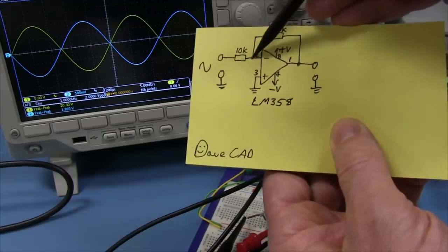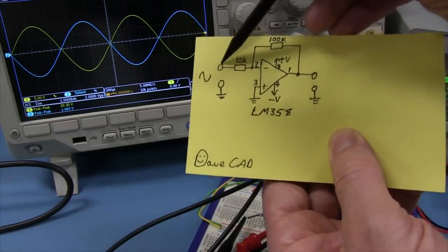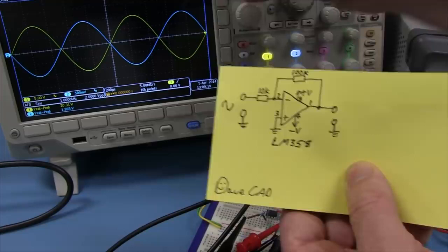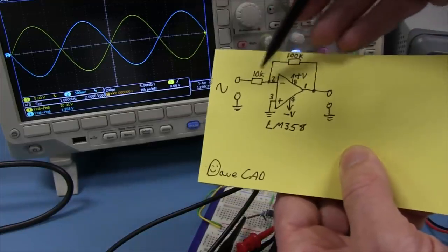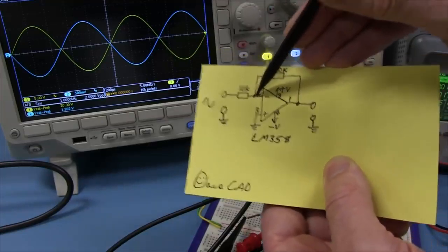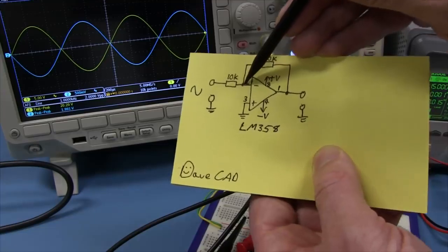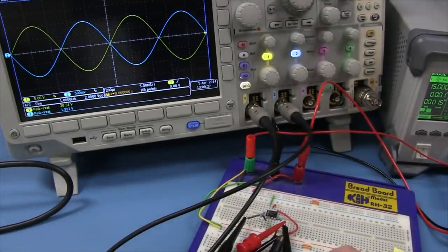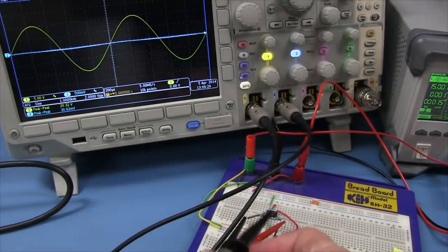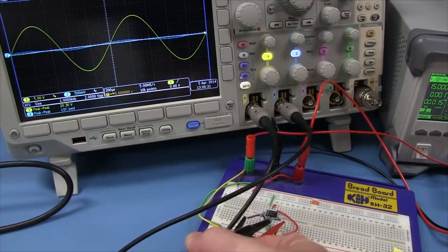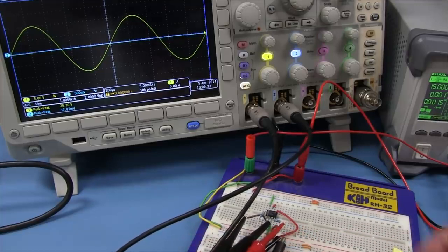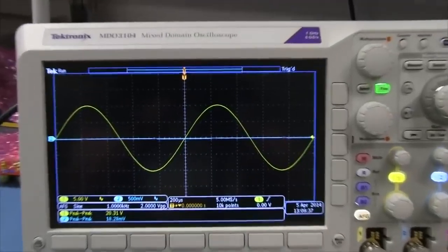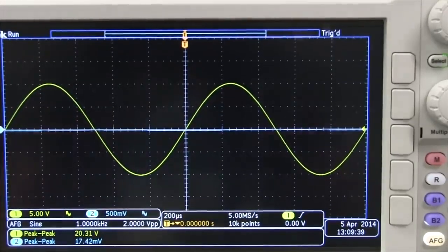Now, you wanted to see the virtual ground, didn't you? What happens if I move my input probe, the blue waveform here, from the input over to this? You'd expect to see the signal. But as I've told you, and as you should trust me, let's move the probe over. That is our virtual ground point. Look, flat as a tack. The signal has vanished. Magic.